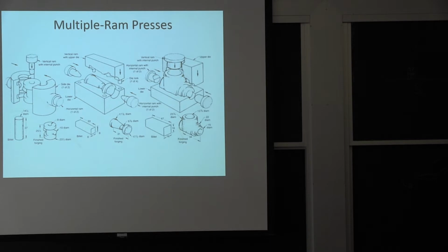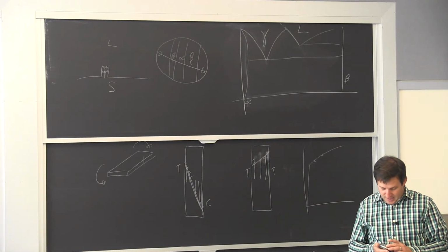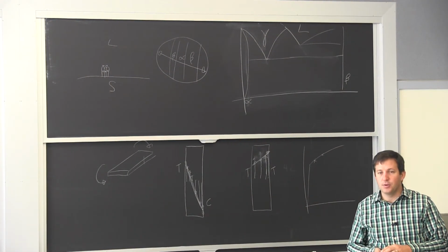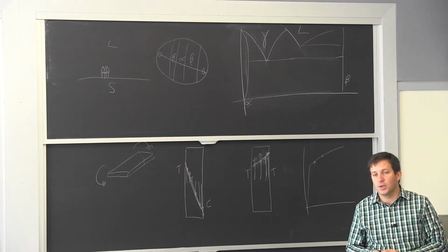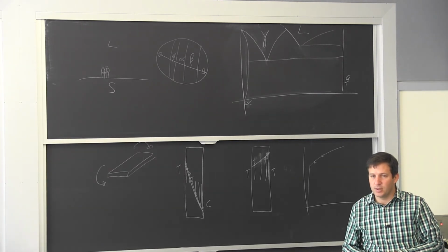So that little piece I had, it's essentially an adapter that you put on a pressure vessel. You weld it on the pressure vessel, so you can thread in, on the inside of that piece, a riser. It's going to be subject to a lot of stresses. It needs to be weldable. So there are a lot of advantages in having it forged as opposed to cast. You could machine it if you only needed a few, but if you need a large quantity, I presume that's the reason why they use forging.